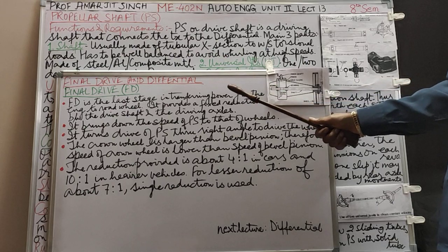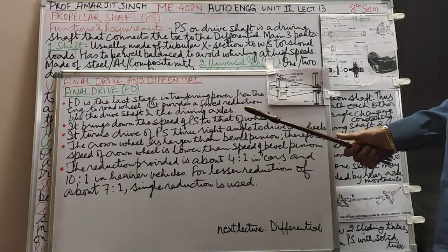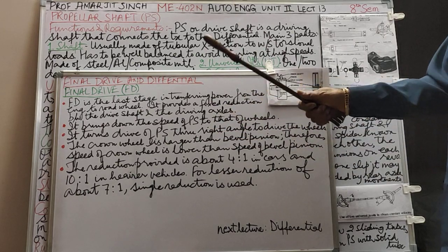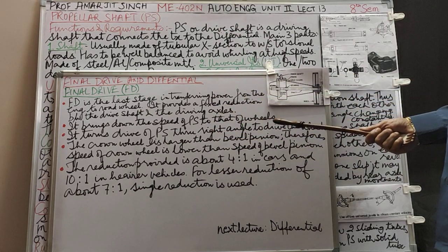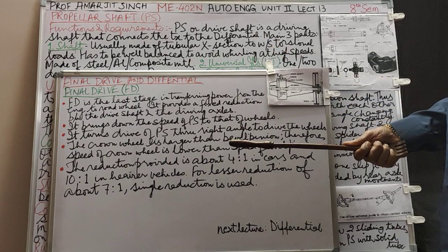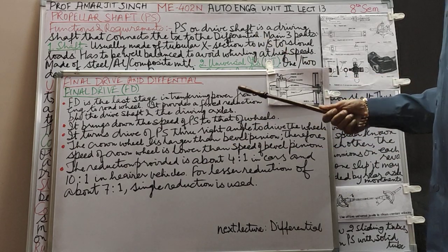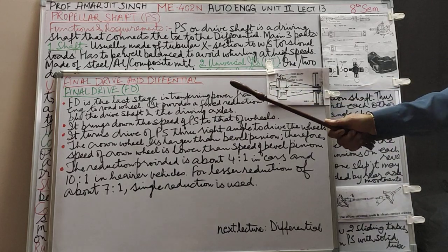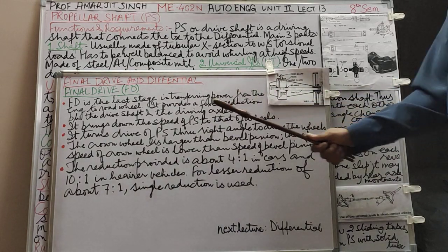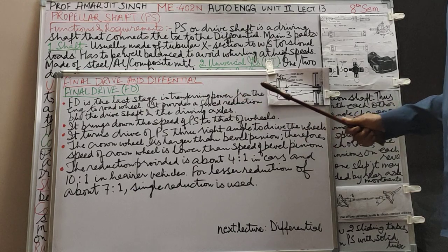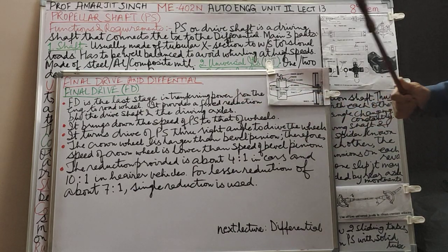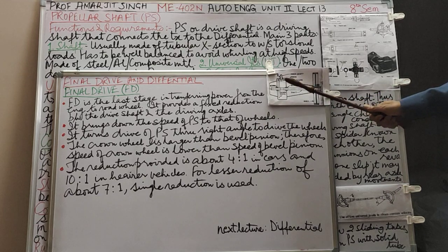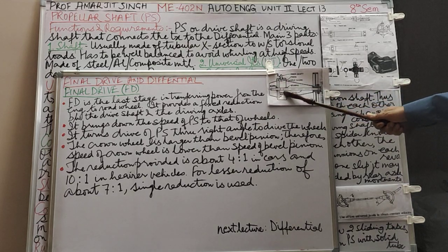There was a reduction there. You know, there are 4 gears and reverse, that's a manual, and the reduction is that much. First gear means what? The gear ratio is the reduction. It's maximum in first gear and least in fourth gear, but the reduction is there. And that reduction in the gearbox is variable. Here the reduction is fixed, because you cannot change the size of the crown wheel.